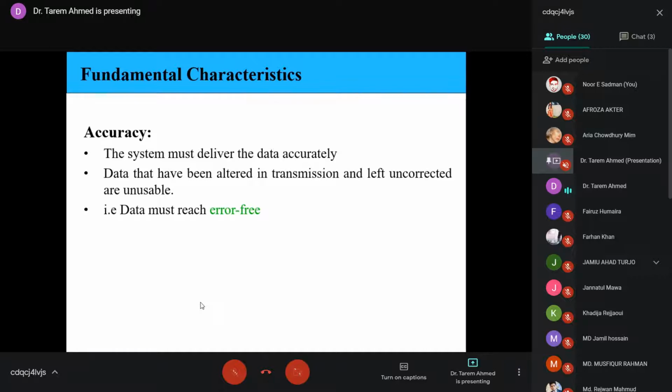So once again, the technical definition of noise is any unwanted signal. And usually when you transmit your signal, the receiver has no way of exactly knowing which is the desired signal and which is the noise. He makes some guesses, and we have designed systems in which the guesses are correct 99.9% of the time. The first way of guessing is that your actual signal will typically be transmitted at higher amplitude. So anything low amplitude is noise, and he filters those out. Typically, he's told the exact frequency, and anything in another frequency is noise, right?